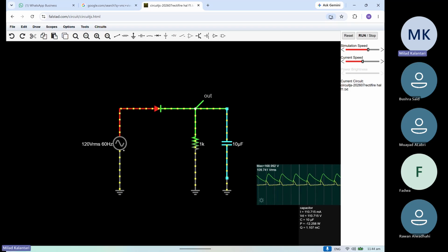So for the other 10 millisecond, this circuit should stay on by just this cap. So the cap should be big enough to make sure that inside the 10 millisecond it can actually provide the current to the load, right? You should choose the cap value based on this.